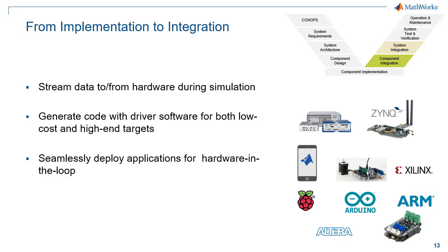Moving up the design V now, let's say you want to get hardware involved. First thing I'll say is that when it comes to hardware, we have the ability to allow Simulink to push and pull information from hardware during simulation. So if you're still over in the design portion of your process, but you have a need to stream data in from, say, a microphone or a webcam, or you want to push data out to some board that is connected to you via TCP/IP, that is perfectly doable. We can interface with hardware at that phase in development.